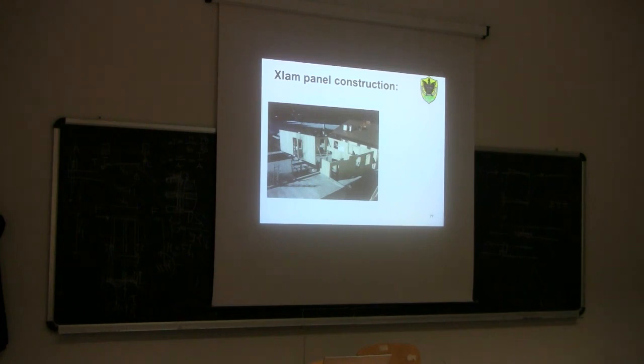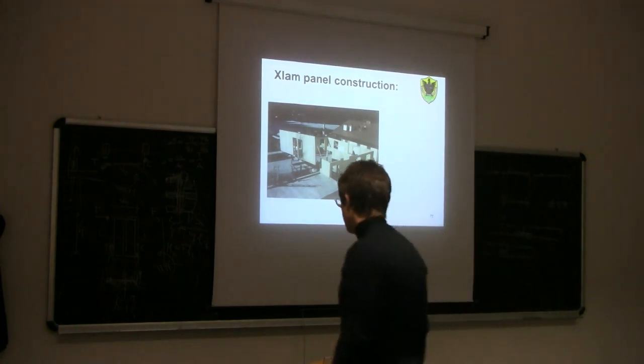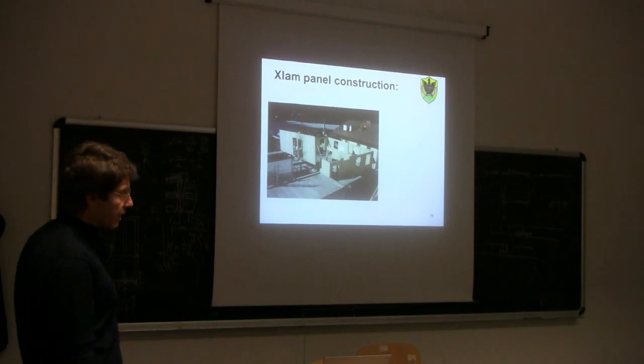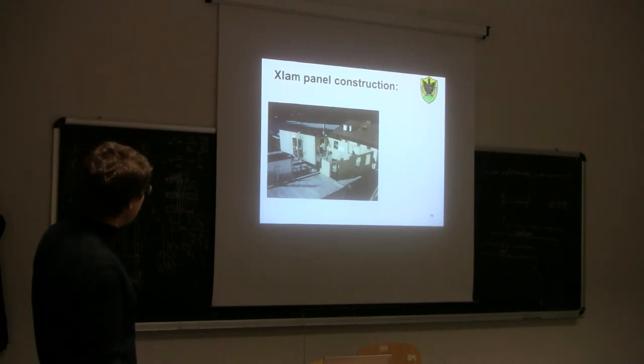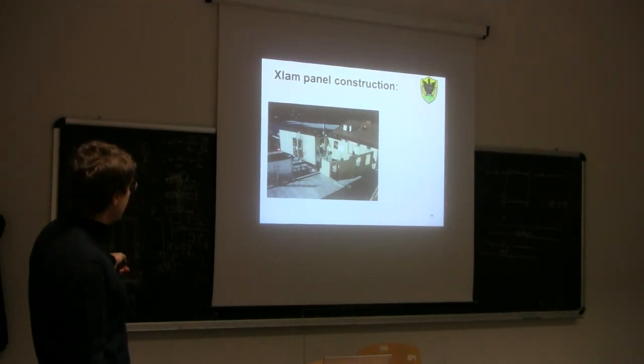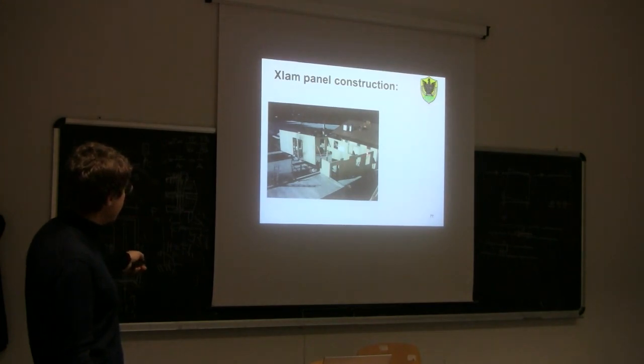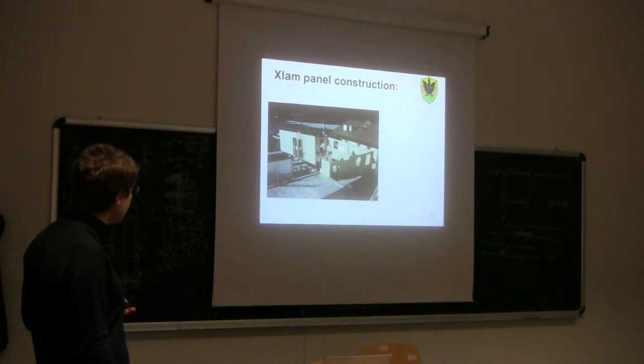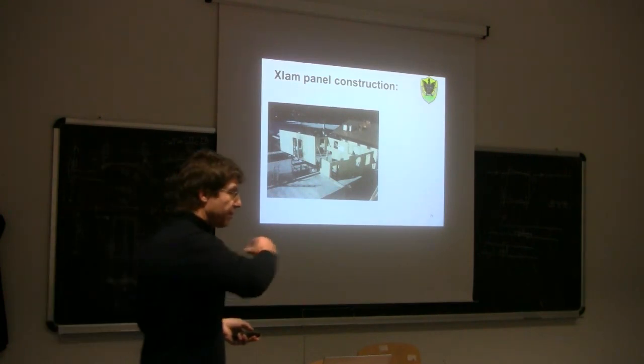This is an example. Very often, again, to take advantage of quick fabrication, the whole wall is already cut, and arrives on the building site with the openings already cut. So, again, you see the placement there. You see also here some temporary bracing. Why do we need this temporary bracing? Because those temporary bracing are needed until we place the floor on top of it.